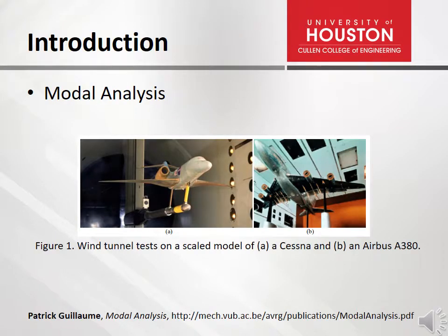Modes are inherent properties of a structure and are determined by the material properties and boundary conditions of the structure. Each mode is defined by a natural frequency, modal damping, and a mode shape. If either the material properties or the boundary conditions of a structure change, its modes will change. For instance, if mass is added to a structure, it will vibrate differently.